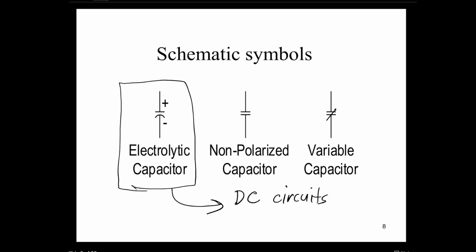And back in the days where we used to do a lot of those labs and building those power supplies, we used to see them blow regularly, and they would just literally explode, and it would be as a result of connecting an electrolytic capacitor on an AC side. So you never want to connect an electrolytic to AC. Okay,